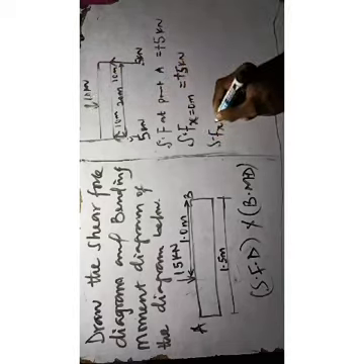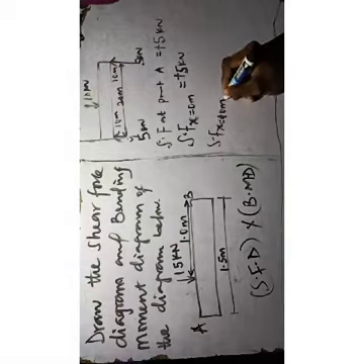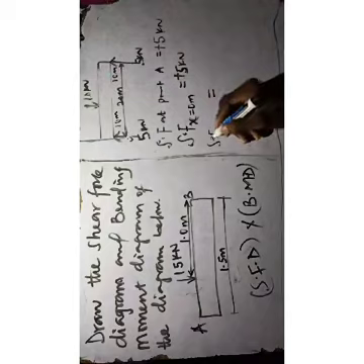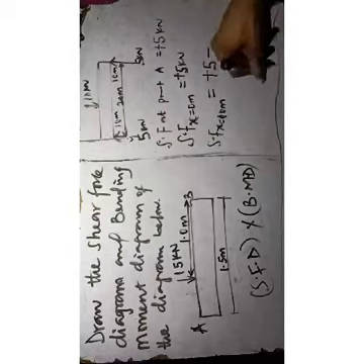So next thing you do is, now the shear force when x equal to what? 10. When you get to the middle, when x equal to 10 meter, the shear force there will now be this one minus this. You see, you are talking about the force, not about the distance here. So that will be the 5 kilonewton. You know it's positive, right? Plus 5 minus, this is acting down, right? So this is plus 5 minus 10. That will give us minus 5 kilonewton. Don't forget, it must come to a balancing.